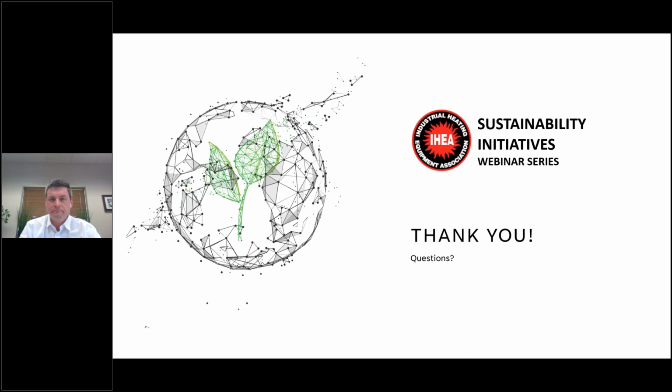Is it okay to consider only carbon dioxide kilograms in your carbon footprint in place of carbon dioxide equivalent for heat treat processes? For the most part, yes. That's what I did in this presentation, I mostly just considered carbon dioxide. If you have any sort of natural gas leaks, you need to consider that as a carbon dioxide equivalent. For the most part, that's not an issue. Your methane and your nitrous oxide production is going to be a lot lower, maybe less than 1% of your total CO2 equivalents.